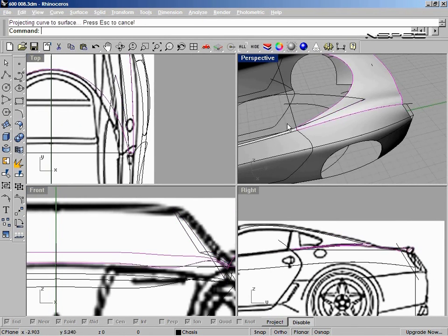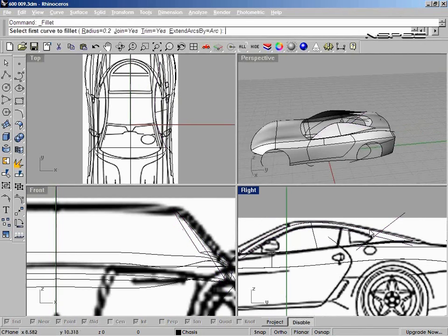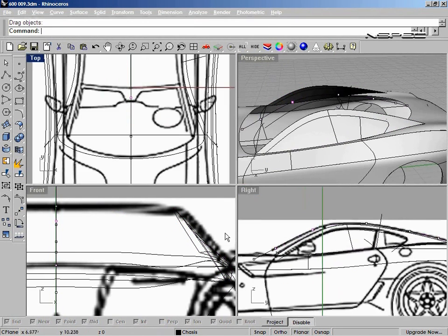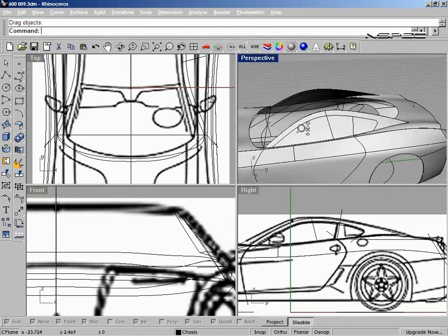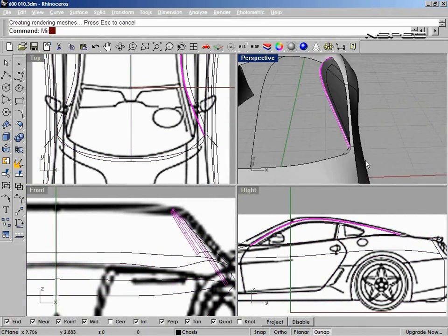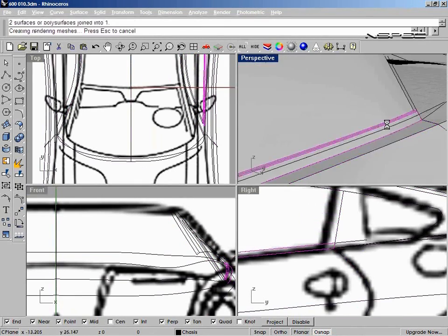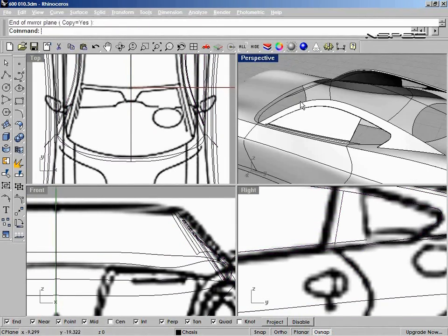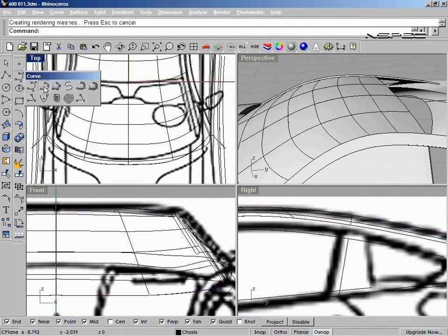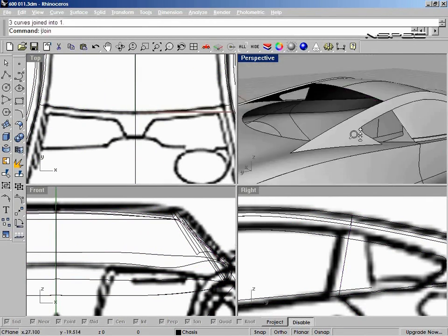Back in the old days, or with polygon modeling instead of NURB modeling, people would like to build the overall shape of the car and then go in and start cutting out the finer details and scooping away. I take a similar approach, but I do it panel by panel instead of the overall shape of the car. It's a lot more precise and intuitive. It just makes more sense to me, and it's a lot easier to correct mistakes, whereas if you're building the overall shape, it's not as precise, I don't think.